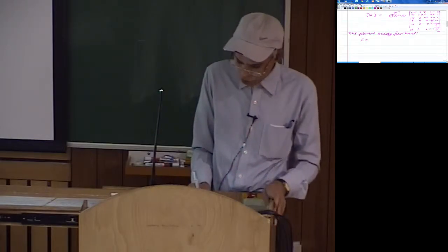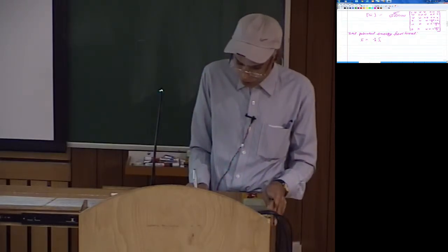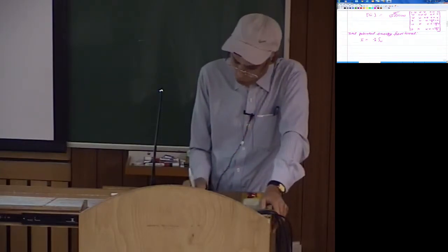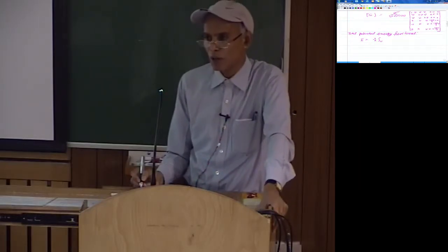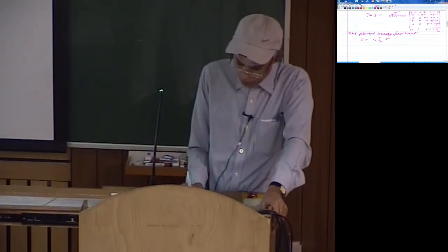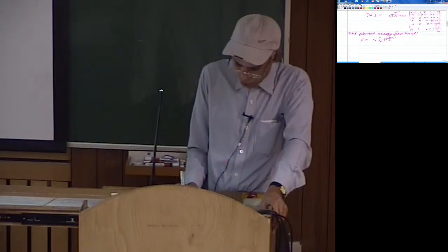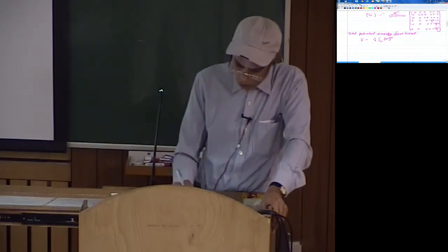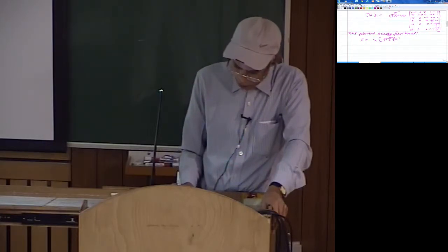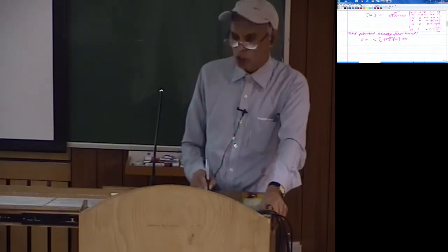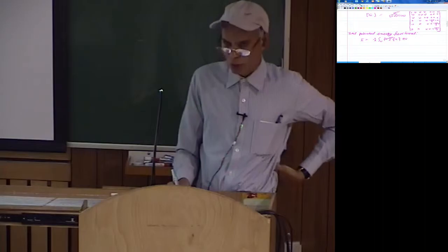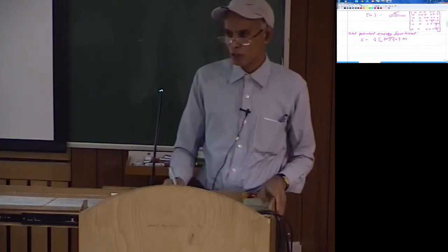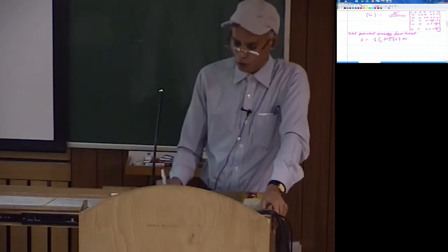So now this is going to consist of, say, I, which is the strain energy, half of integration over volume, capital V I am using for volume, and this would be sigma xx into epsilon xx plus sigma yy into epsilon yy and so on. So we can write that as sigma transpose into epsilon dV. So this is your strain energy part, which is actually half of sigma xx into epsilon xx plus sigma yy into epsilon yy plus sigma zz into epsilon zz plus gamma xy into tau xy and so on.